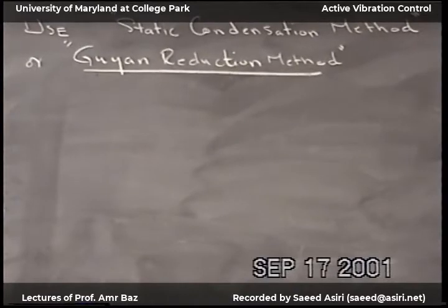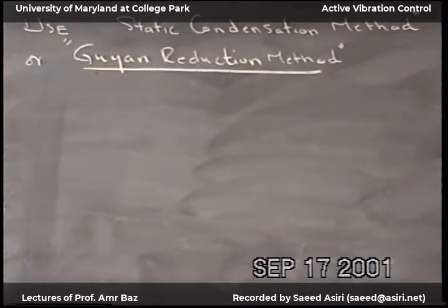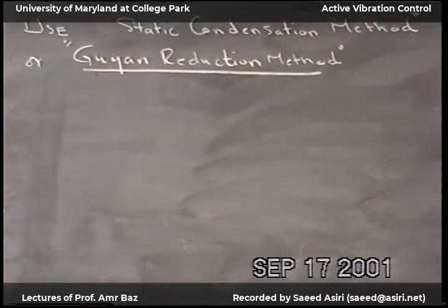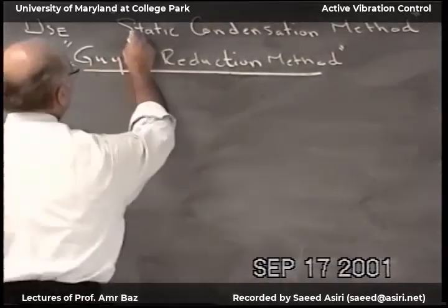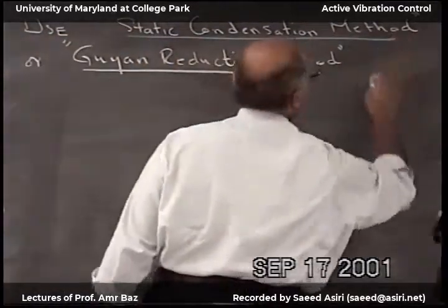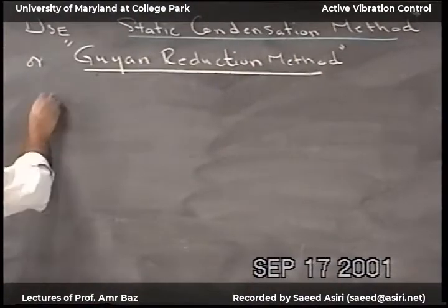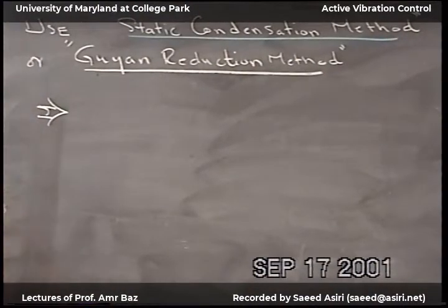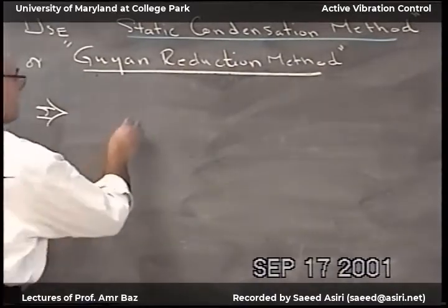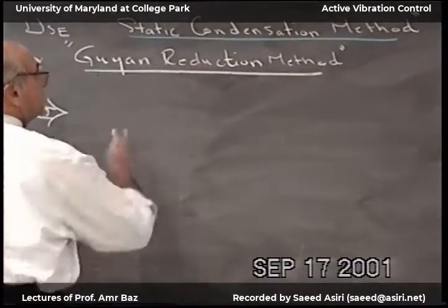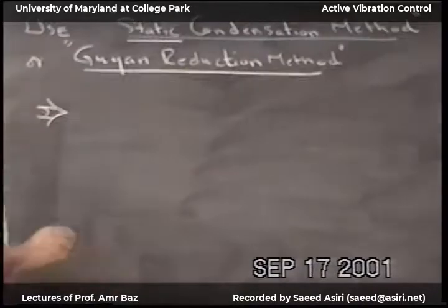Last time we showed that the Guyan reduction keeps the information regarding the potential energy of the system. We said nothing about the kinetic energy. We'll do it today. And all this is done for the static condition. Okay, so now we will say the following. We'll say now, neglect the dynamics and only look at the statics.